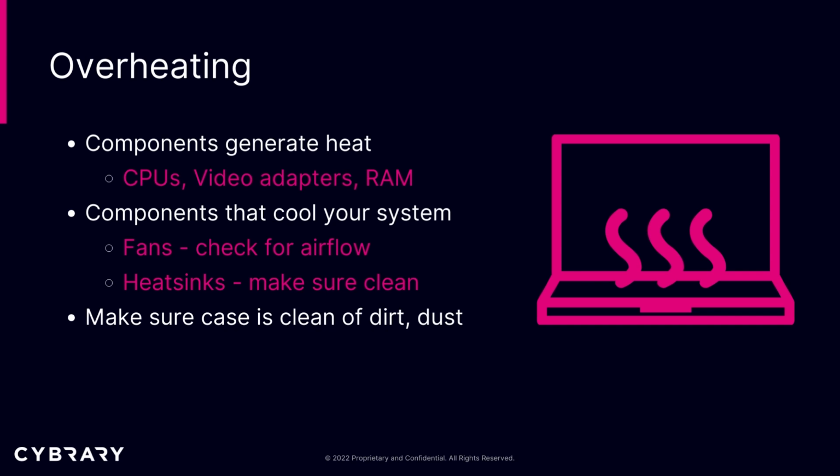The heat sinks on your CPUs and on other devices help cool those devices. Make sure the heat sinks are clean and dirt free. There's no dust or debris on the heat sinks. All of these help with the airflow and help cool the components off in your case. And make sure that the case itself is clean and free of dust and dirt.